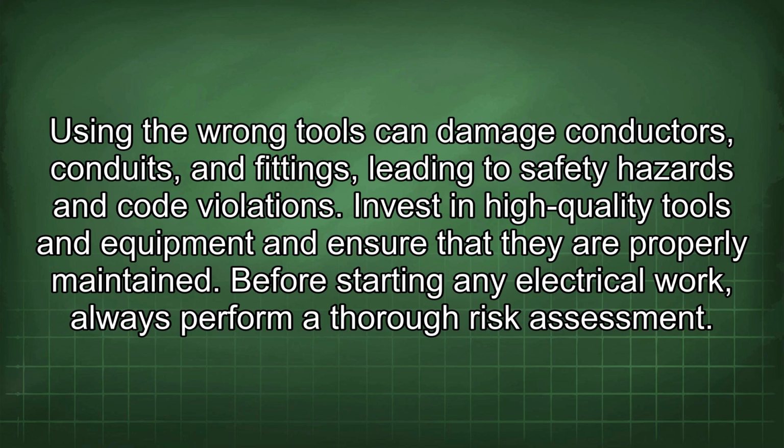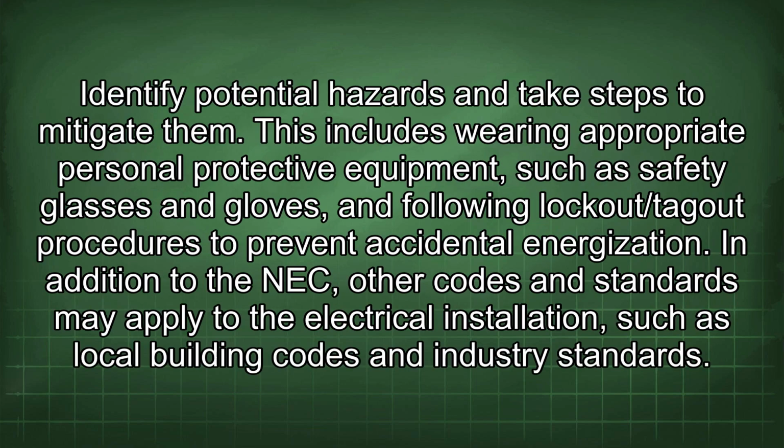Before starting any electrical work, always perform a thorough risk assessment. Identify potential hazards and take steps to mitigate them. This includes wearing appropriate personal protective equipment, such as safety glasses and gloves, and following lockout/tagout procedures to prevent accidental energization.